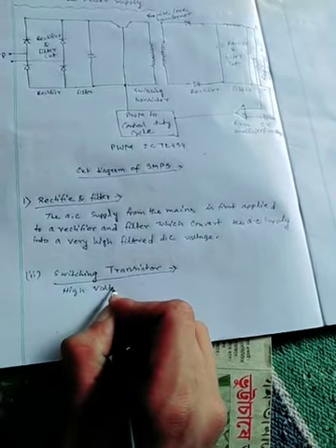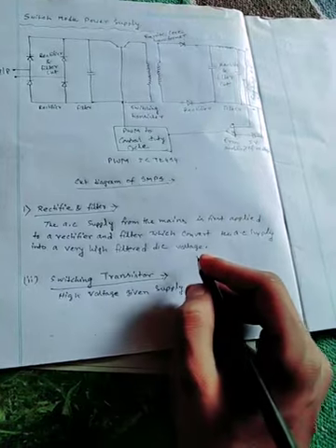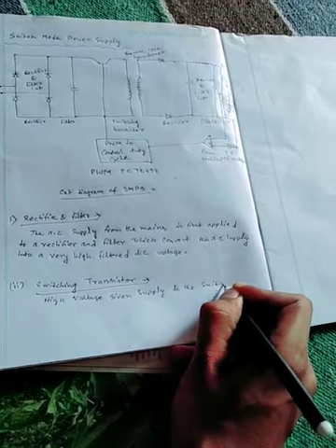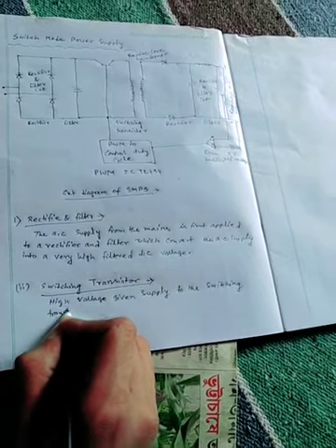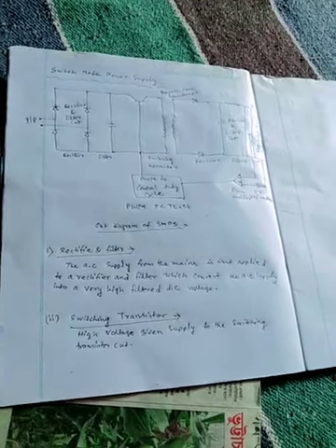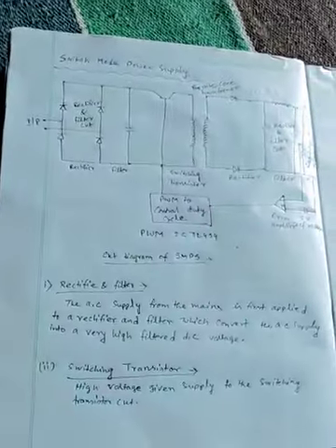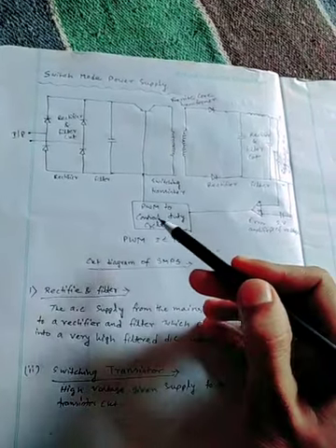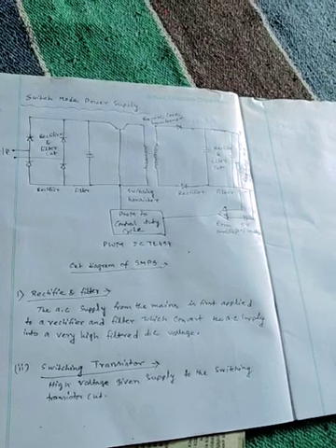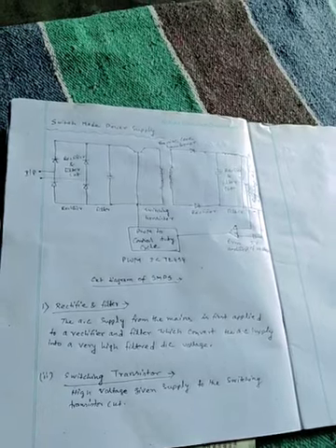The switching transistor is switched on and off at very high speed by the PWM. PWM, pulse width modulation, generates very high frequency square pulses. The switching transistor circuit switches the high voltage DC on and off at the same high frequency, resulting in a square pulse output.